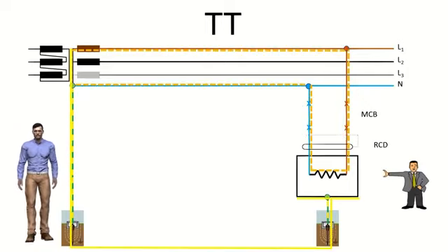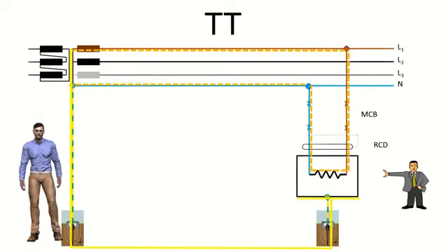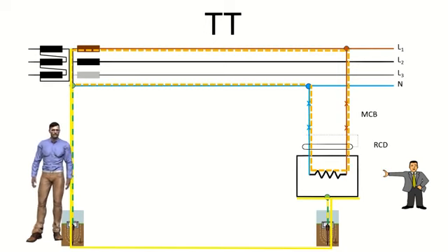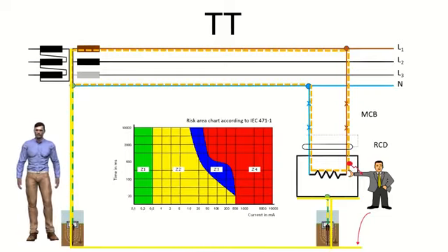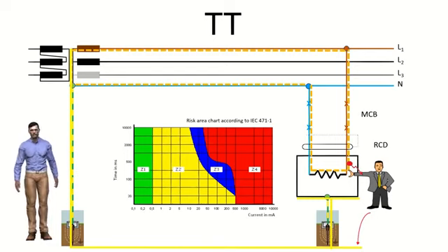In the case of the 30 mA differentials used in homes, its reduced current and its opening speed will also serve as protection against direct contacts downstream of the differential. If the installation works at 230 volts and we consider a body resistance of about 1000 ohms, then, if we did not have the 30 mA differential installed, the earth leakage current through the body would be about 230 mA, enough current to cause problems if the current is not interrupted in time.